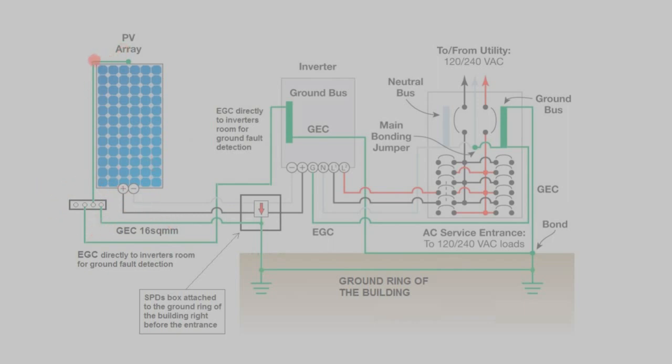So instead of the ground going from the metal frame to the rack to the box frame, we're just making the ground inside this box. And then that's carrying the equipment ground to the metal inverter box. And then this is also going, maybe that's a permanent crimp, but it's also being connected to the ground bus on your main service panel.